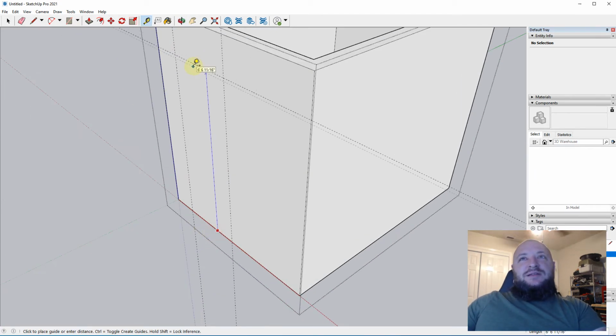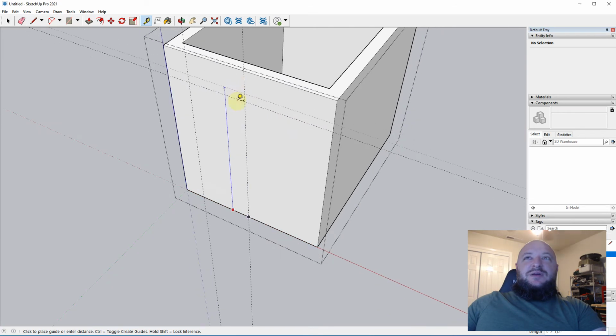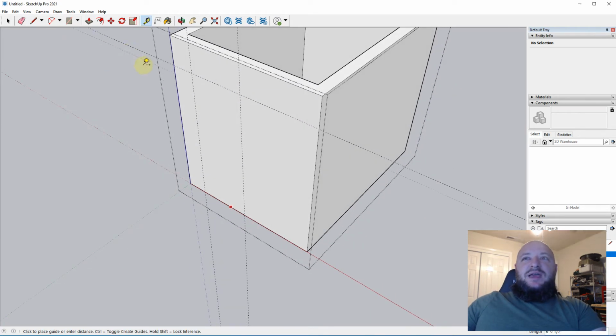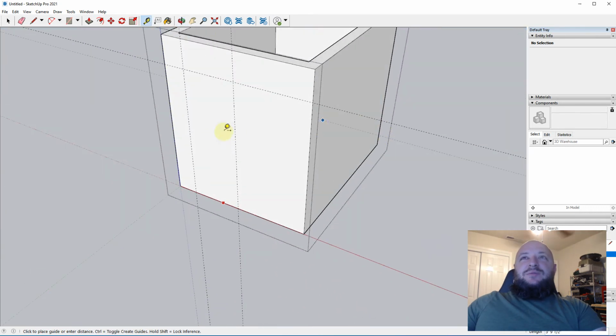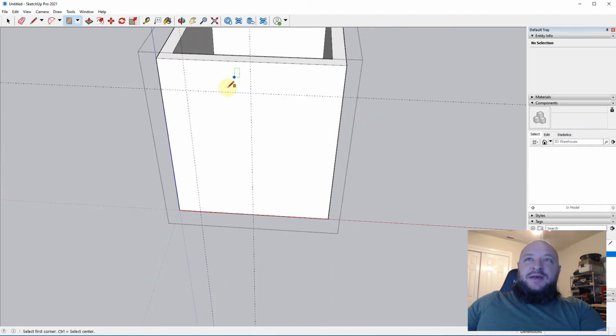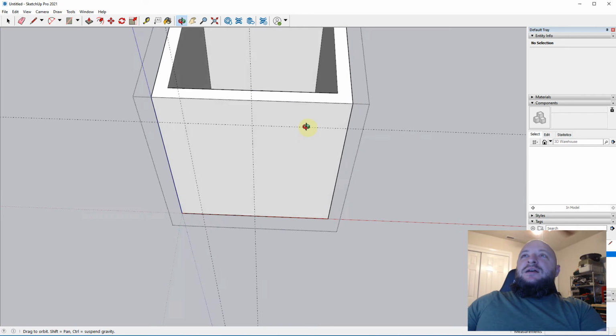They moved it up here, the distance is right, but then all of a sudden we move the camera and this thing's a fraction of a millimeter off. You always want to be referring points really accurately in here so that you make sure your model's 100% square, you're working with 90-degree angles, everything's accurate and tight, okay? So if you don't get an intersection at one of these spots when you go to draw it, you've missed one of the lines and you'll probably have to go back and redraw.